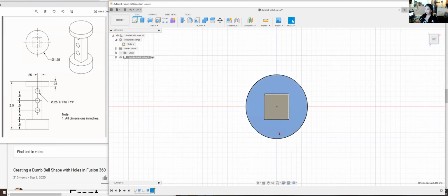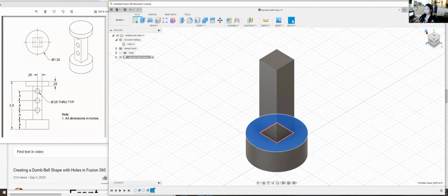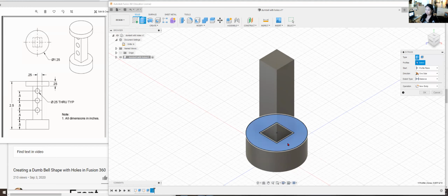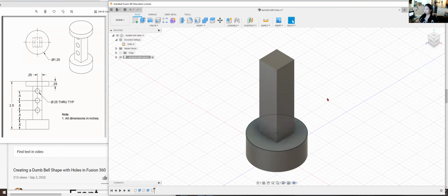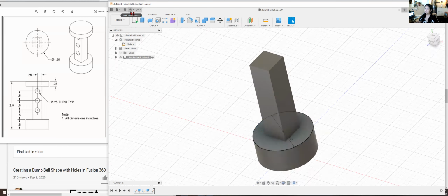See, if I highlight it, I only do the sketch on the bottom of the cylinder. See that? That's not what we want, because if I hit E, it's just going to push up that, and we don't want to push up that. Okay. So hopefully I didn't confuse you. So I'm going to hit undo.